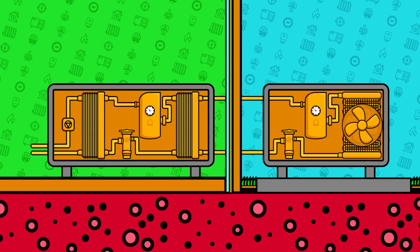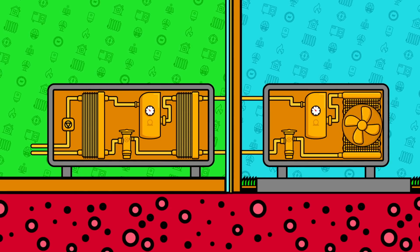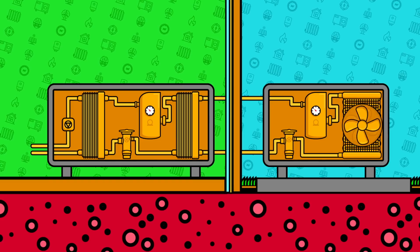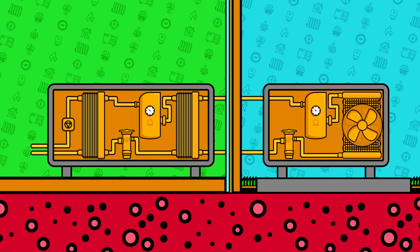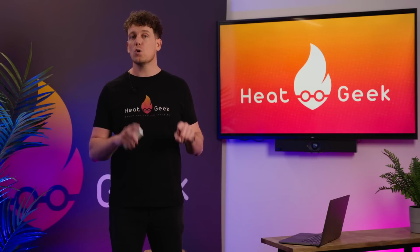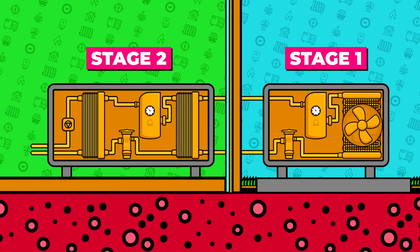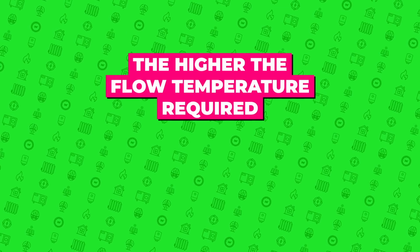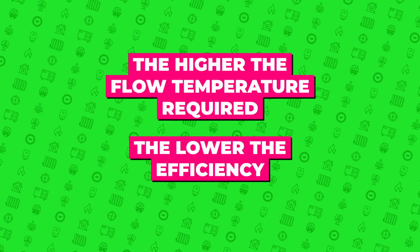The last variant of heat pump to be aware of is high temperature heat pumps. As the name suggests, high temperature heat pumps produce higher flow temperatures, which can be helpful when heating more difficult properties that may have limited space for emitters or restricted insulation. High temperature heat pumps achieve this with two compression stages, the second additional stage taking a separate refrigerant to a higher temperature. These are less efficient, however. The higher the flow temperature required, the lower the efficiency.